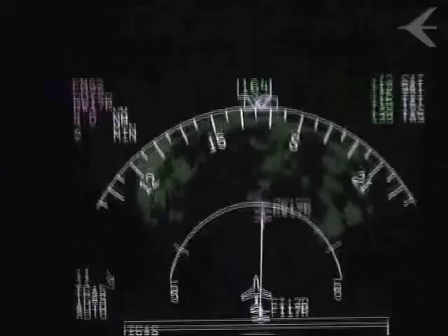When flying at low altitudes, rotate tilt upward frequently to avoid flying under a thunderstorm. The shorter the range, the greater the tilt. When flying at high altitudes, tilt downward frequently so as to avoid flying above storm tops. The shorter the range, the lower the tilt angle.